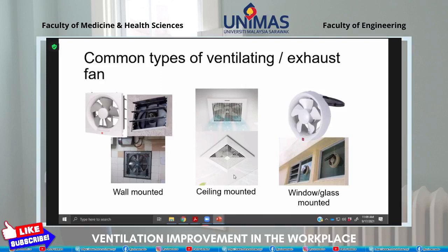And then we have ceiling mounted, normally mounted on the ceiling. You can see a lot in toilets. If you see toilets without windows and without any openings other than the door, most likely the installation will be done through a dedicated ducting system with a ceiling mounted fan. And in some installations, it is quite hard for us to go through the wall, so we can go through the glass or windows. This is window mounted and glass mounted.